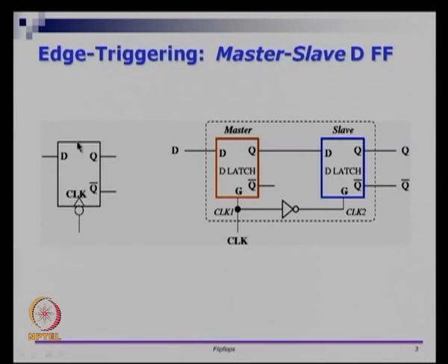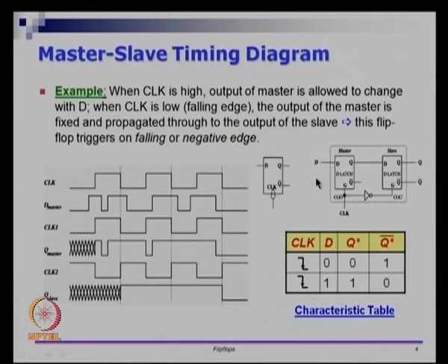So if you see a rectangle with 3 pins for D, Q and Q bar and just a triangle like thing, that is a positive edge triggered flip flop. In the positive edge triggered flip flop, D is being sampled only when the clock rises. In the negative edge triggered flip flop, D is sampled when the CLK signal falls. So once you do this, CLK1, CLK2 and so on do not matter. You can now think about this whole circuit, this D flip flop, as a black box.